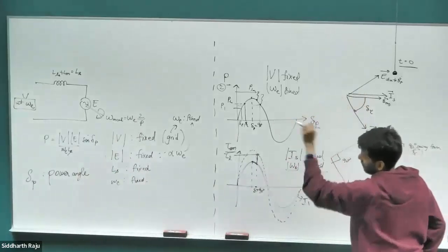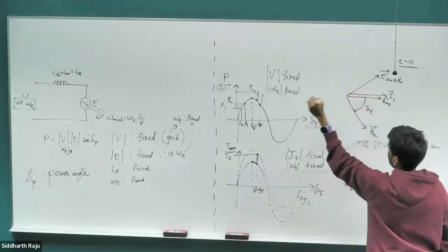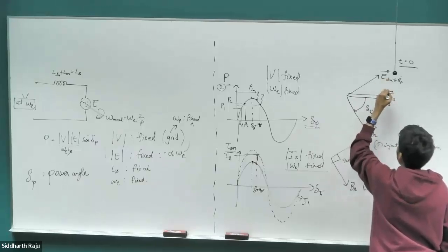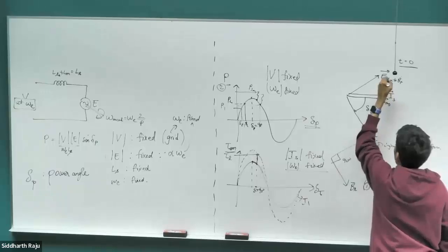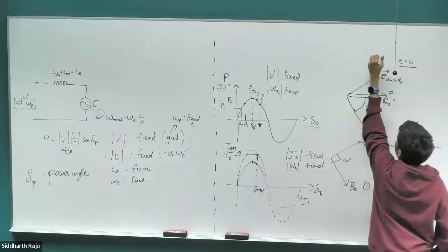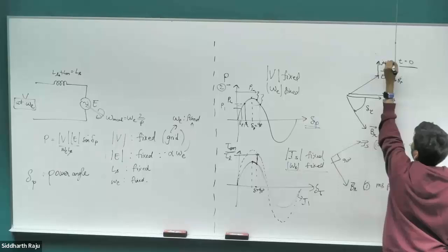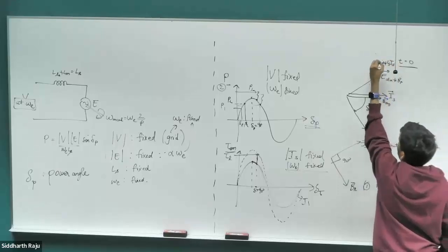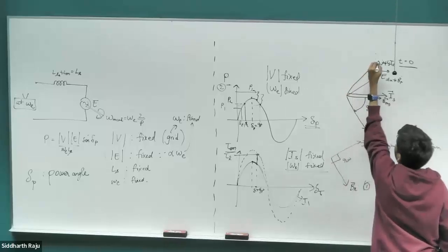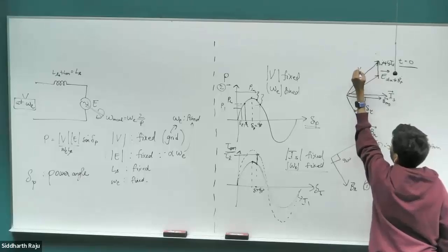So for the simplified circuit where we don't have any resistance, we have j omega Ls drop, which should be 90 degrees along the EMF, sorry, Is. So Is is like this. So j omega Ls would be along this direction, which should be added on top of the EMF. This is going to be j omega e Ls times the stator current, and the net sum of this plus this is going to give you your terminal voltage space vector.